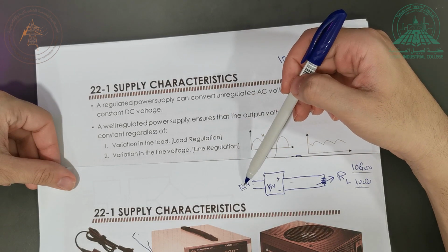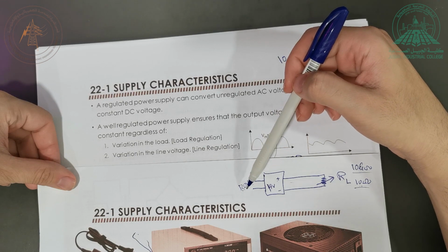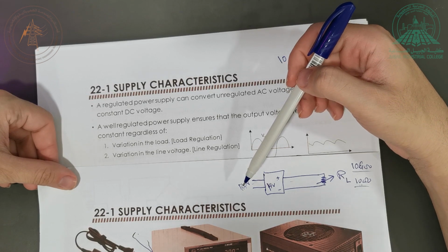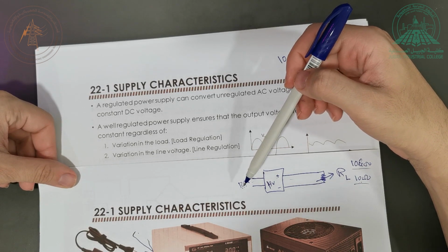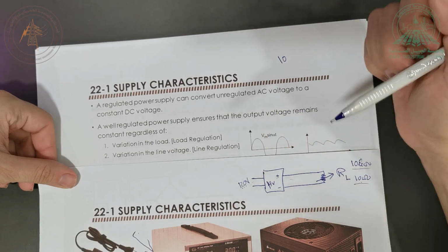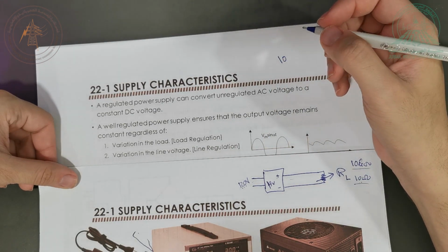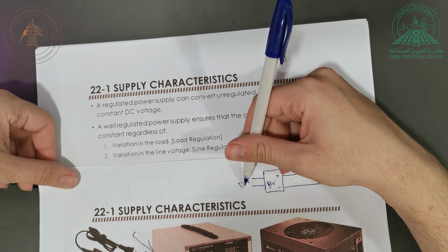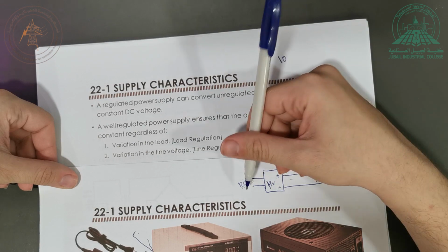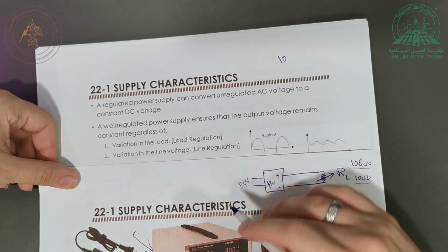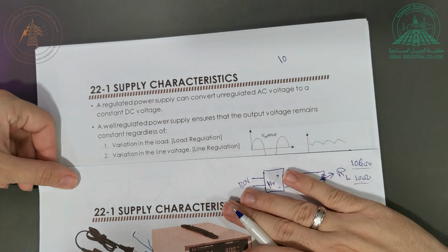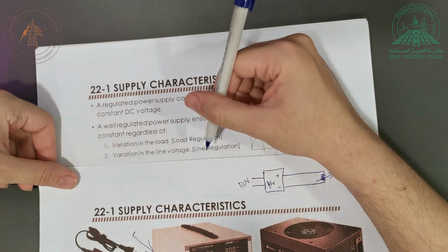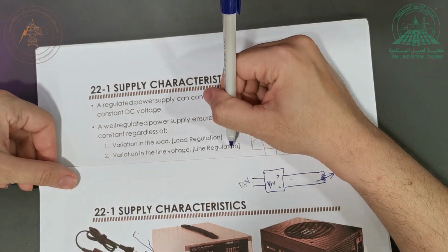So even if the line voltage varies a little bit, fluctuates, and this especially occurs in rural areas, like far villages and small towns. This can happen, especially in poor countries. This is quite typical to happen, very common to see. So a good power supply, a regulated power supply should be able to give me this 14 volt, regardless of the fluctuations that happen here. If this goes up to 125, goes down to 115, still I should get 14 volt here. Okay, so this kind of regulation is called the line regulation.